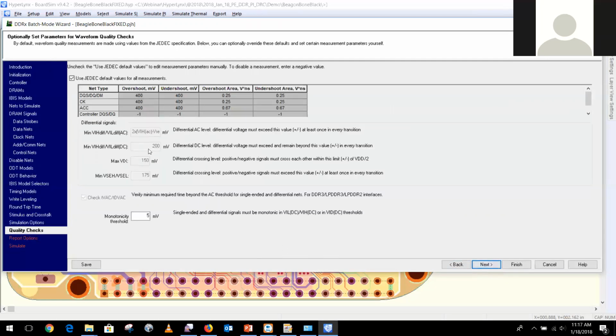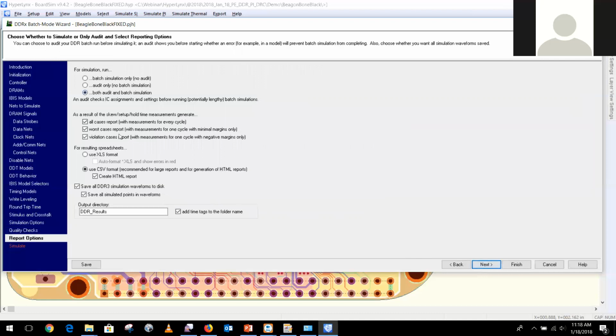And this is what I mean in terms of JEDEC checking. Right? So JEDEC defined a standard for DDR2, DDR3, DDR4. All these measurement values, these parameters, these terms, VIX, minimum VIH, overshoot area, undershoot area, and a bunch more things, particularly for each different memory interfaces. And the tool will automatically grab these numbers, these limits, measure the signal, compare against these JEDEC settings, and tell you if it pass or fail. Now think about doing it that way versus doing things manually, where you simulate the signal, see the waveform, instrument your cursor, take down the measurement, add, subtract, multiply, whatever, and then compare that to JEDEC. Painful, right? Automation, let the tool do it.